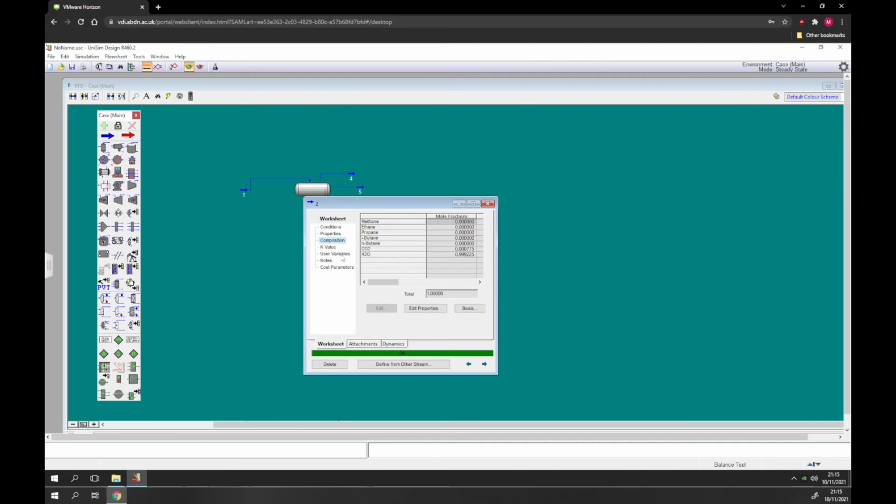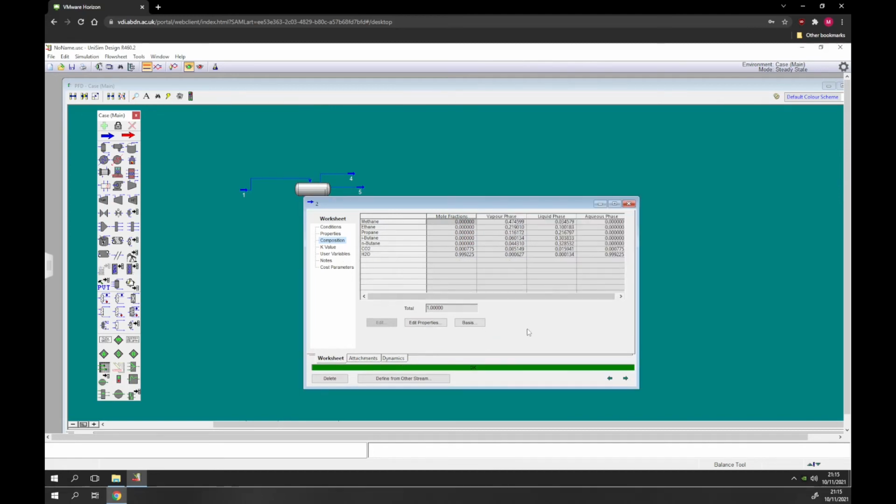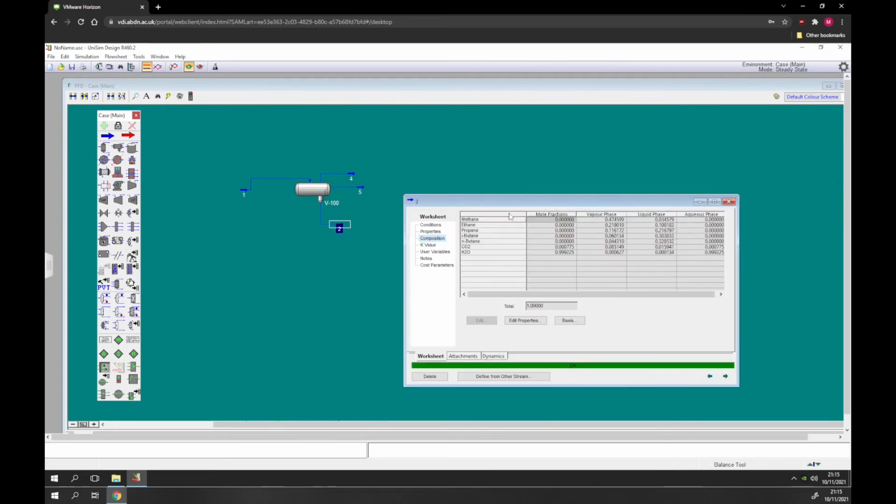So I was a bit wondering about the value, but you could see some of the CO2 is dissolved in the water. One of the things you will note though is there's no composition overall of any of the oils. So the Peng-Robinson equation of state, this is a great example of it, just ignoring all oil and assuming all the oil comes out in the oil phase and not in the water phase.